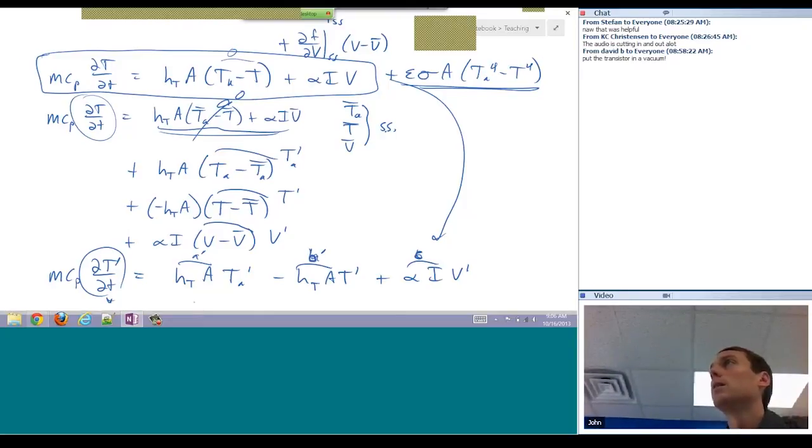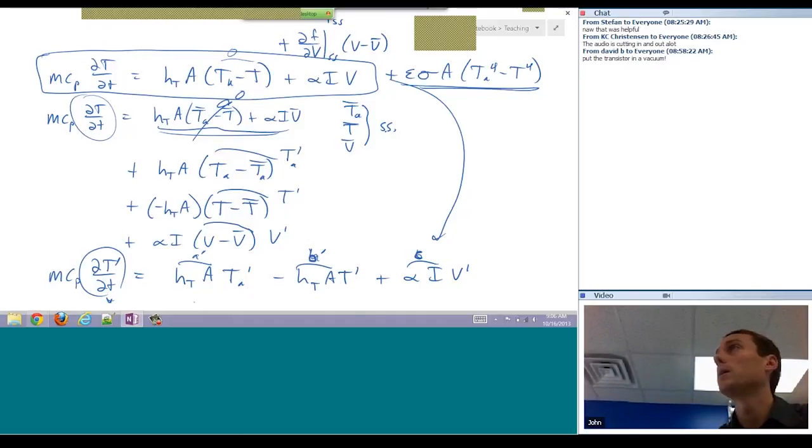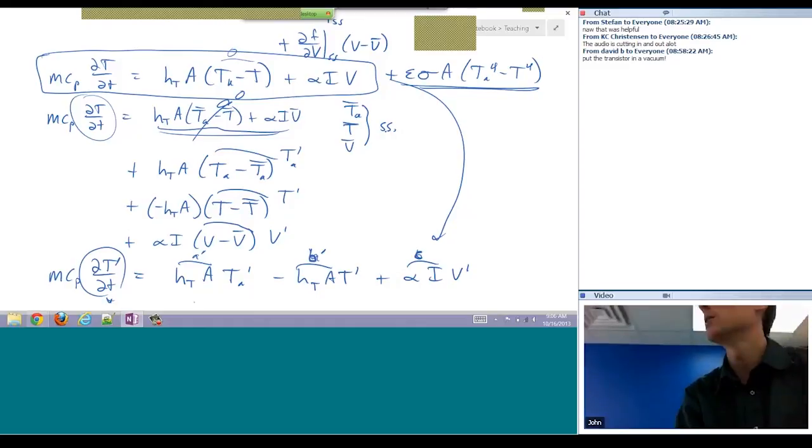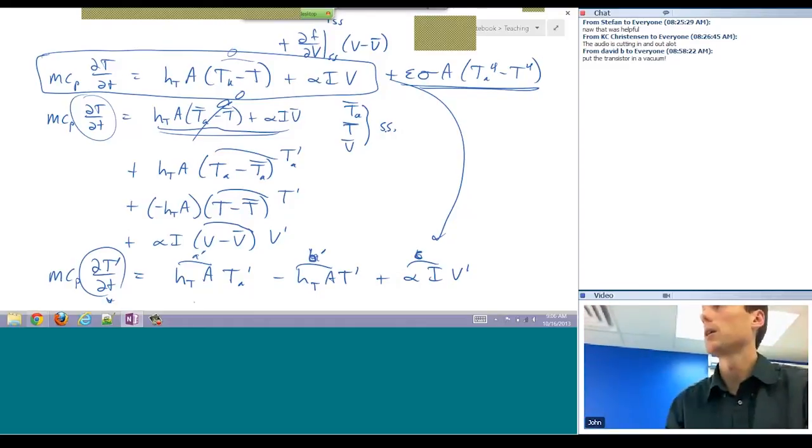Yeah, that makes it nonlinear. You have to linearize it for your homework. I think that's due today. You guys had that where you have to linearize your model before you can take the Laplace transform, because you have 2 variables multiplied by each other. So wind speed times temperature or something like that. You've got to linearize it so you can separate those variables, and then you can take the Laplace transform.